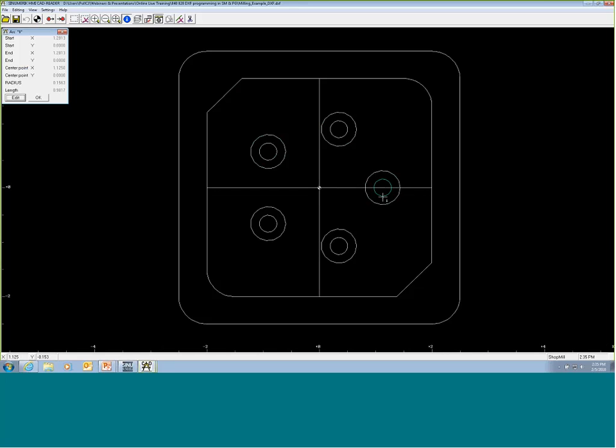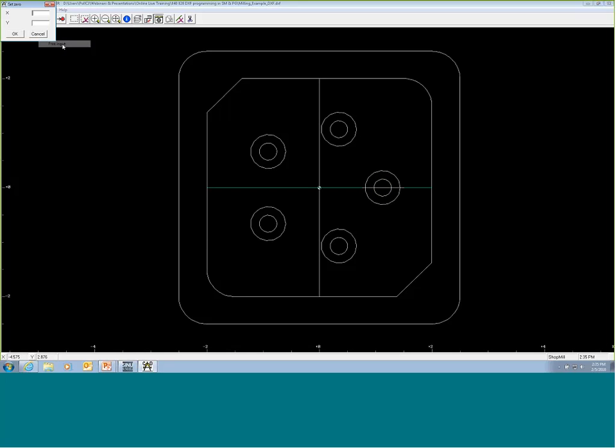If I pick this center of that circle, I could see, okay, the center point I know now is 1.125 away from this feature that I just found. So if I need to get it there, and I don't have the luxury of modifying the program or the drawing through some of the drawing utility, I could go back to my bullseye, go to my free input, and tell it, okay, let's move the 0 based on an actual position that I know. So you can manipulate things that way as well. You can get kind of creative if you have a known specific spot where you have to force this 0 to be.